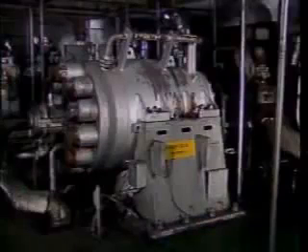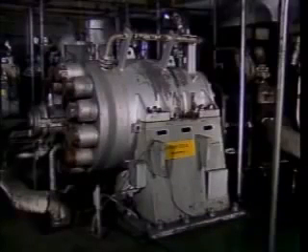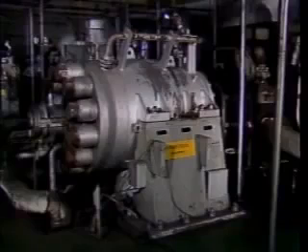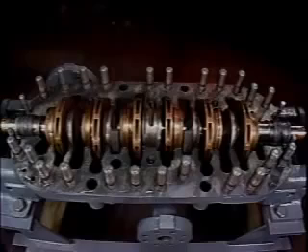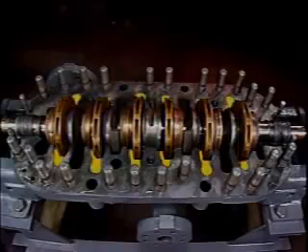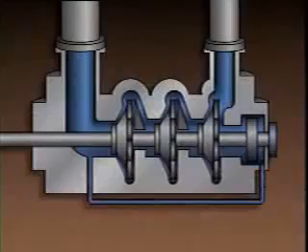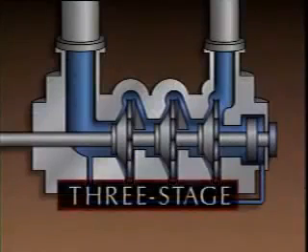This force moves the liquid through the pump and increases the liquid's pressure. In applications where large increases in pressure are needed, multi-stage centrifugal pumps are often used. A multi-stage centrifugal pump contains 2 or more impellers and volutes in a single casing. Here's a simplified cross-section of a 3-stage centrifugal pump.